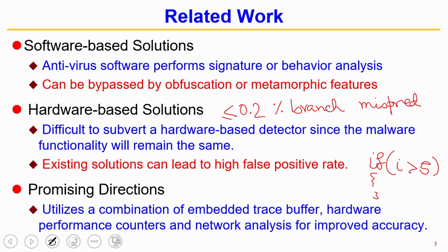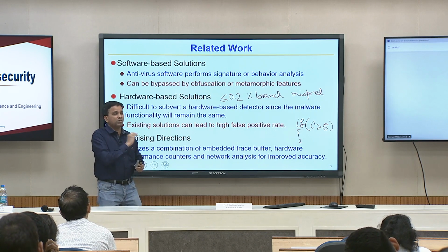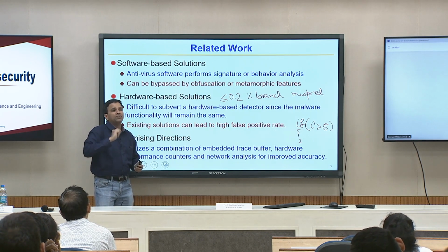That is where hardware based solutions become useful, because the instruction that gets killed as a no operation, the hardware knows about it. So it is not going to count those branches that were mispredicted and never used. It will only count the ones that were used. If I take the example of the human, we should be asking them to get rid of their clothes. That would be analogous to a hardware based solution. We get to the rock bottom of the instruction that actually gets executed.